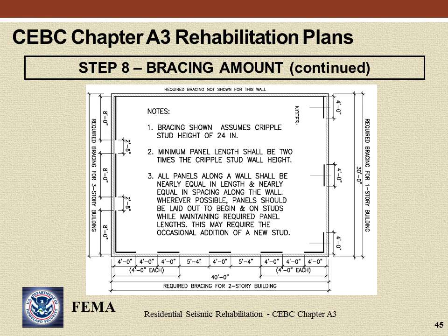1. Must have a width not less than 2 times the sheathing height. 2. Install bracing as close as possible to the intended location where obstructions occur. When the requirements for bracing cannot be met, an engineered design will be required.